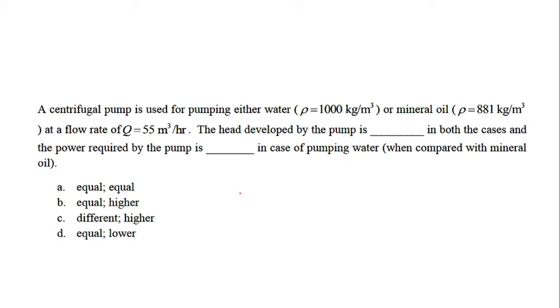No, actually for a particular centrifugal pump, the head developed is independent of the density. It is dependent only on three things: impeller diameter, then frequency, and the flow rate. It is independent of fluid property. Head developed by a pump is independent of fluid property.